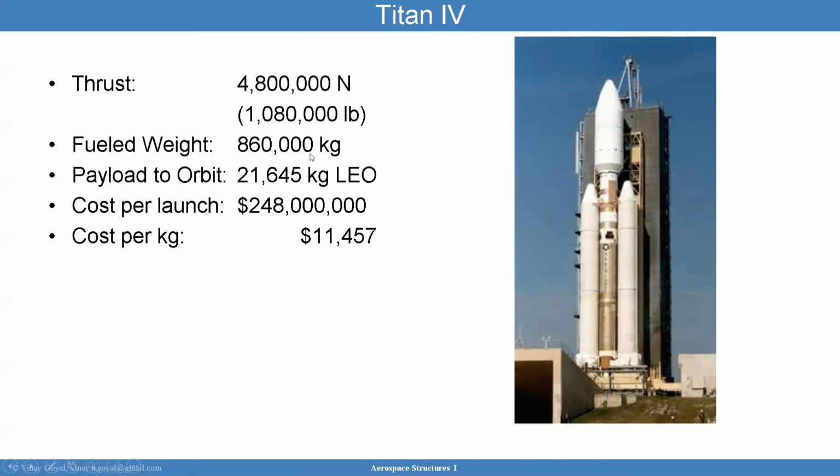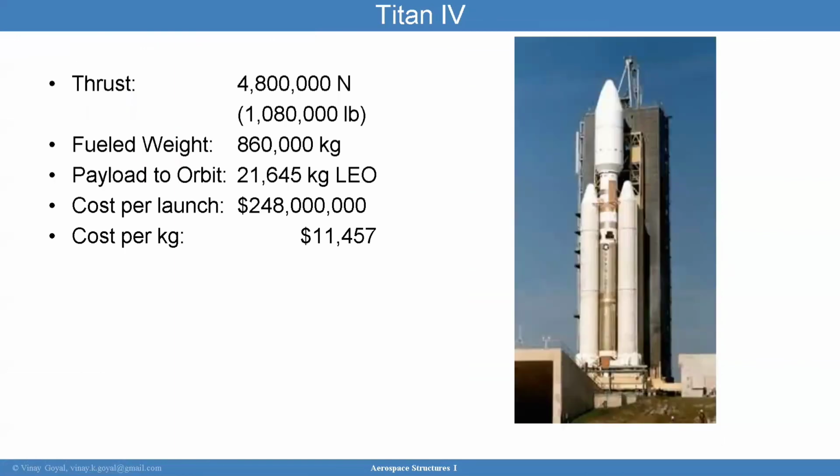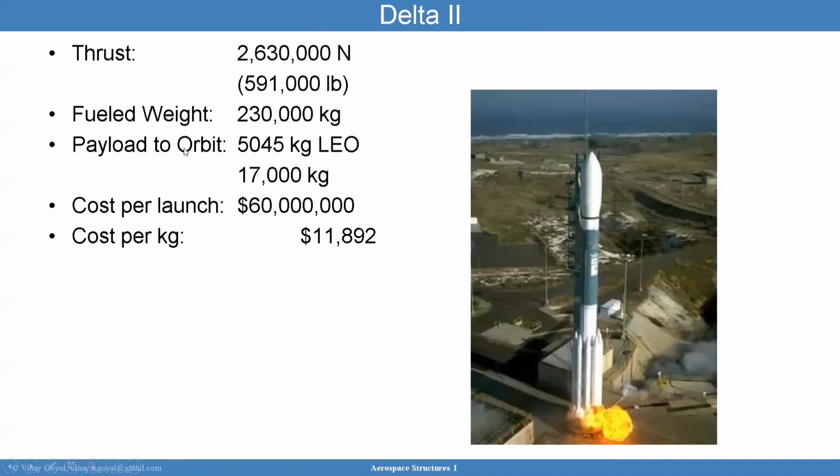Looking at thrust divided by weight can help to see what's going on in terms of how much thrust I can produce, but ISP really gives the information you need. Typically, this thrust to weight ratio will be about 10 times greater in thrust than weight. You will see that very often. The Delta II here,